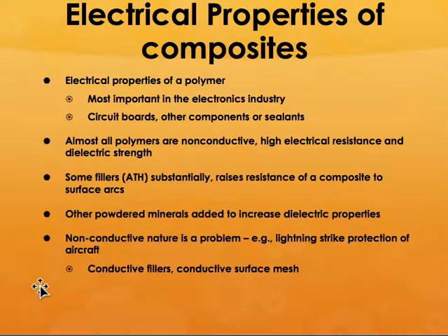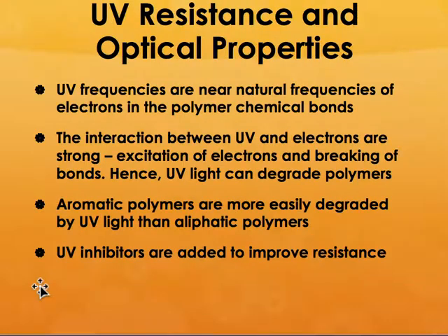And that will have to be repaired by bringing the aircraft back into your repair place, and doing that and putting it back, which means you have to remove the entire area and you have to replace the entire conductive surface mesh. So those kinds of properties are required. So these things are extremely important. You don't actually think twice about it when you have a metallic structure in an aircraft type of application. But in a composite, you have to think about it all the time.